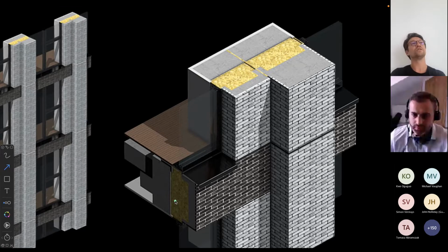For other projects, you will be dealing with three different contractors. For example, for traditional masonry, you get a glazing contractor positioning the window in one location, a precast concrete contractor, and a rain screen contractor doing another thing, and you need to assemble it all together, run the dew point calculations, and get the fire engineer to verify that the cavity is compartmentalized properly, etc. Whereas with a precast concrete prefabricated building, everything is done by one contractor, and you are talking to one person.